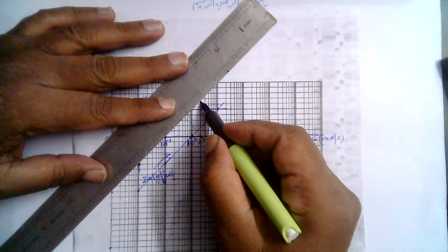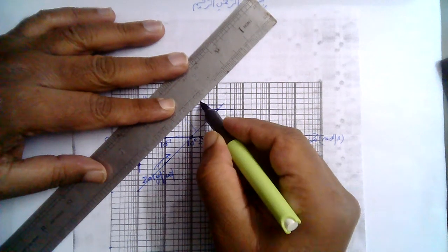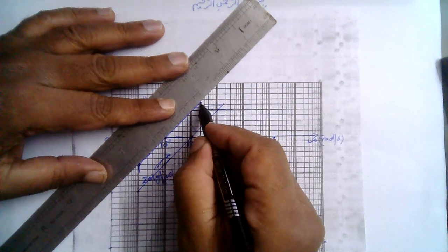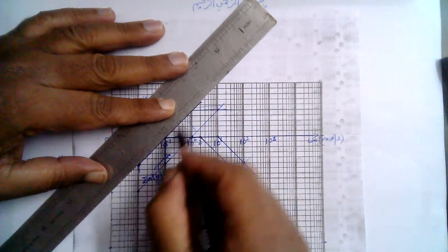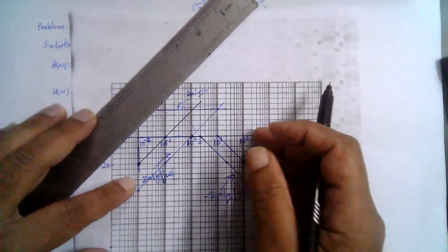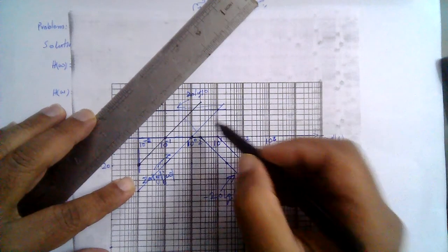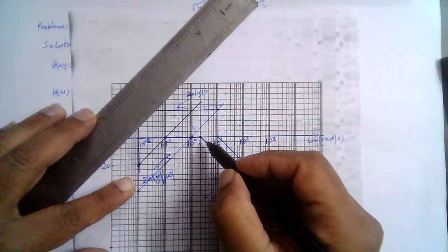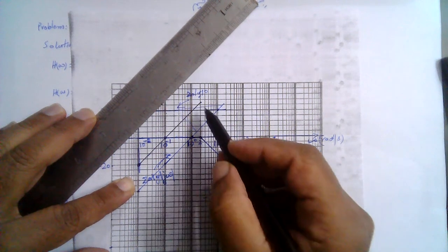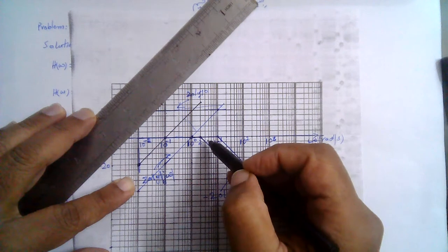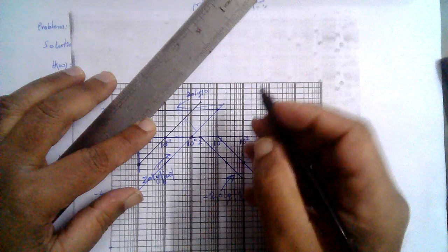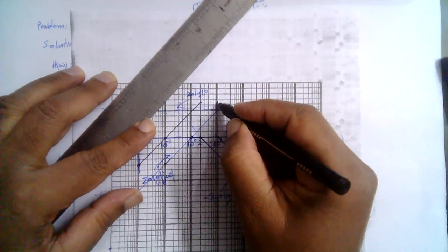Let me draw the resultant plot with black. So this line is 20 dB per decade. Then at this corner frequency we get a minus 20 dB per decade added to the previous 2 asymptotes. So this minus 20 dB per decade will cancel out the positive slope, and this will become a horizontal line till the next asymptote, till here, right?